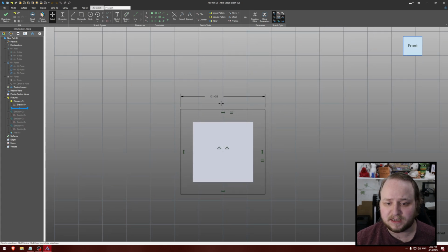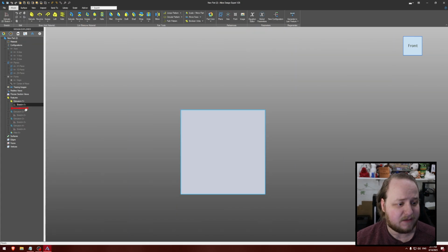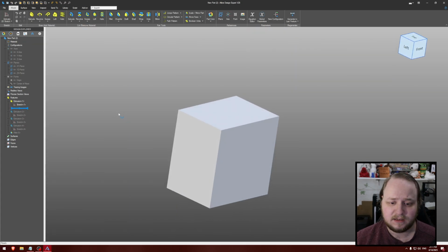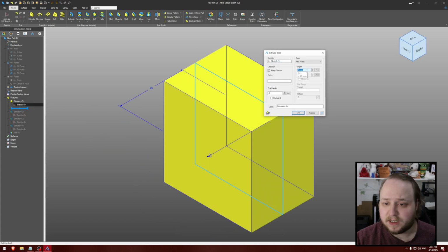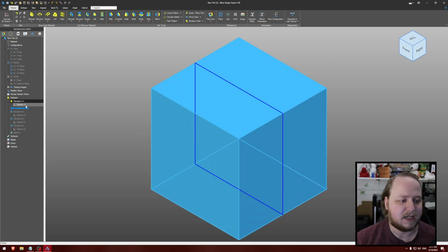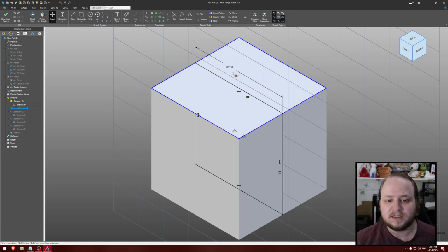And because we set this to be equal, it will still be equal on both sides. I'm then going to deactivate my sketch. And you'll see that our extrusion isn't actually also 35. I'm actually going to change this depth here to be D1. That's the same dimension label that it had for the sketch here.